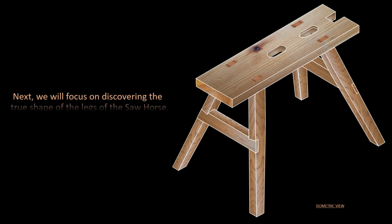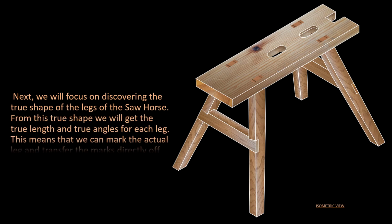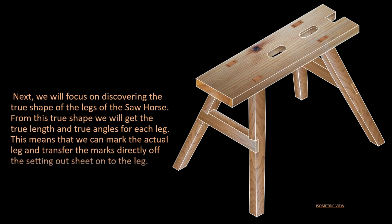Next, we will focus on discovering the true shape of the legs of the sawhorse. From this true shape, we will get the true length and true angles for each leg. This means that we can then mark the actual leg and transfer those marks directly off the setting out sheet onto the actual leg.